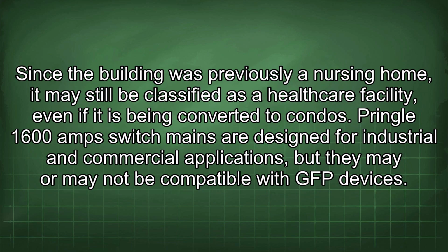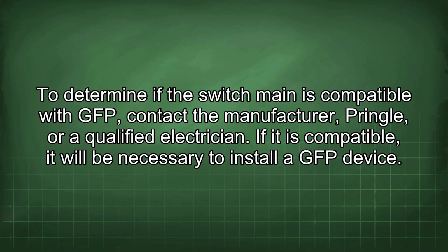Since the building was previously a nursing home, it may still be classified as a healthcare facility, even if it is being converted to condos. Pringle 1600 amp switch mains are designed for industrial and commercial applications, but they may or may not be compatible with GFP devices. To determine if the switch main is compatible with GFP, contact the manufacturer, Pringle, or a qualified electrician. If it is compatible, it will be necessary to install a GFP device.